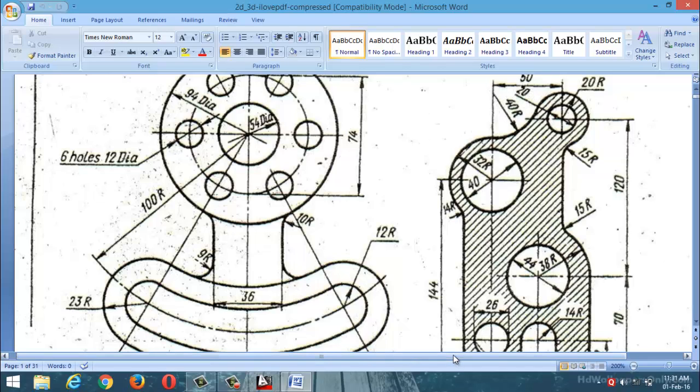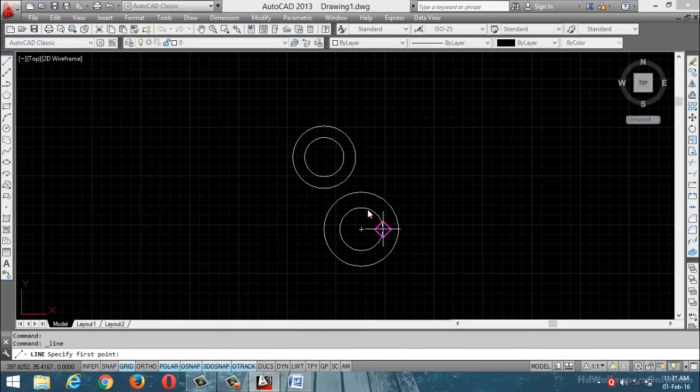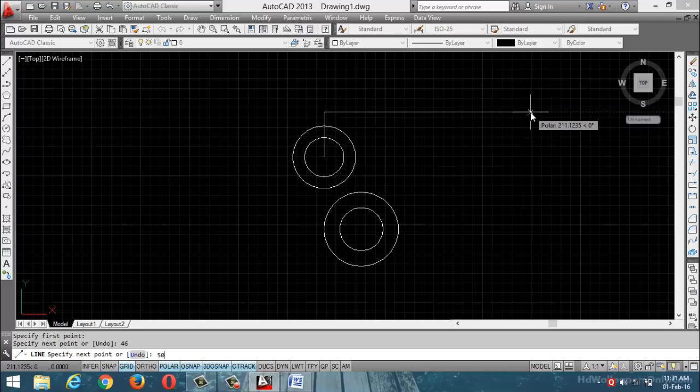Again you can use any type of reference. Now I am going to directly select the line from this center point. Height equal to how much? 120 minus 74, 46. Again in this direction 50. Directly you can use this. Or otherwise, one more reference with respect to this center point: total is 120, then in this direction 12. Same thing. You can use any one.